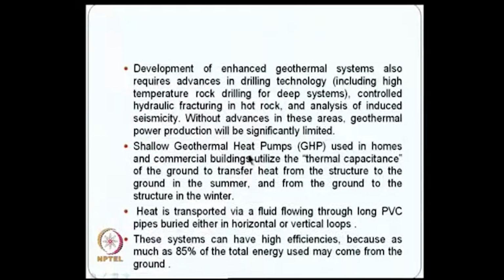So, the other concept that I just mentioned was shallow thermal geothermal heat pumps used in homes and commercial buildings. They utilize the thermal capacitance of the ground to transfer heat from the structure to the ground in the summer and from the ground to the structure in the winter. This is what people are trying to use in the UK and other places. You try to have a thermal capacitance system beneath the buildings, so that you have some sort of transfer mechanism. You try to store when it is available, and also when you need it, take from the